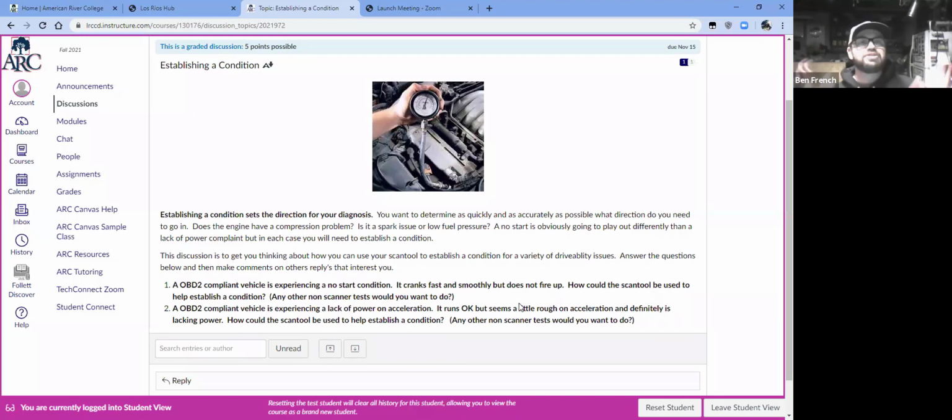So long story short, after it got a complete carburetor rebuild and I got the car again, I ripped out the oxygen sensor and drove the car, and it had a whole bunch of power back. And so that's how we figured that out. But anyways, lack of power acceleration could be like a restricted fuel filter.